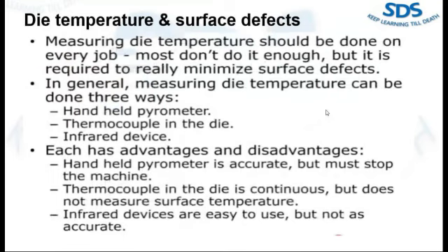Measuring die temperature is necessary for every job, especially on a new die or after major repairs. The die temperature should be measured. Many plants actually measure die temperature several times a shift or every job. It is a key process parameter.